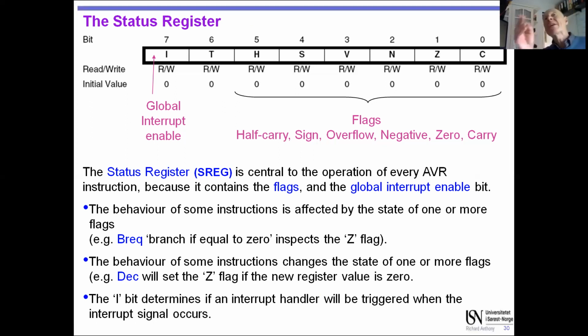If you're comparing temperature values, and your temperature value is stored in degrees Celsius, and it never goes above, say, 50 in your greenhouse, for example, then you've got a value that goes up to 127. You never have a problem, right? You don't need to worry about this in your code, because your greenhouse cannot be 128 degrees, so you won't have a problem with this.